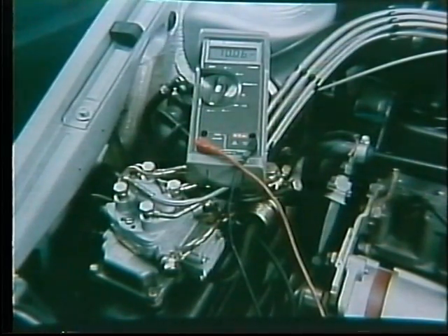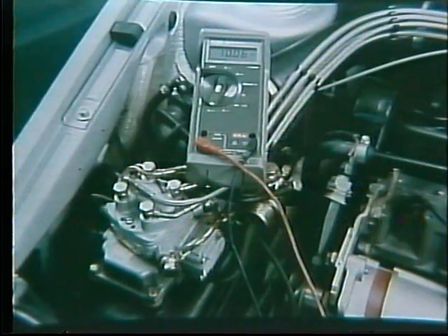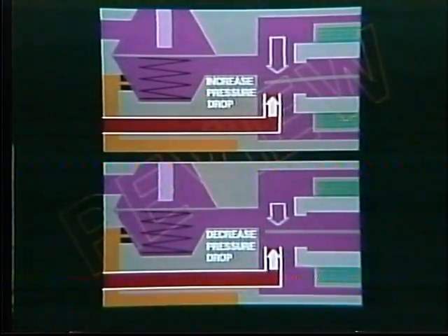Using a digital meter, you will be measuring the small current, in this case 10 milliamps, that operates the electromagnet. It's important that you realize that 1 milliamp is 1/1000th part of 1 ampere, and milliamp currents like this are adversely affected by oxidation on connectors. You may stop now for review of magnetic force and metering by pressure drop.